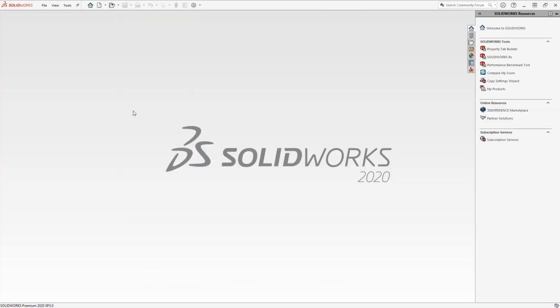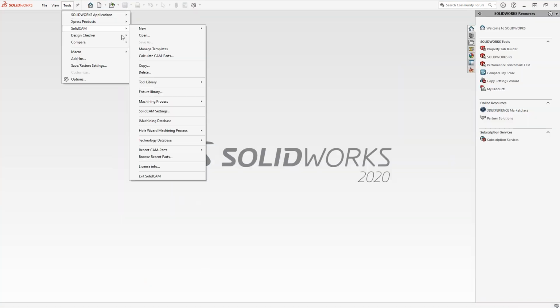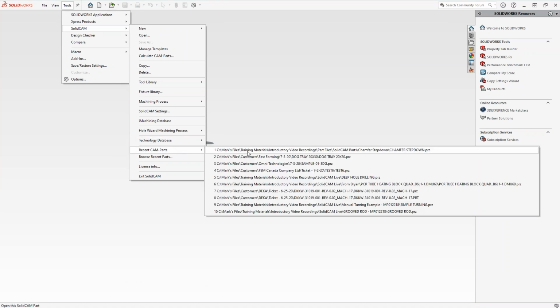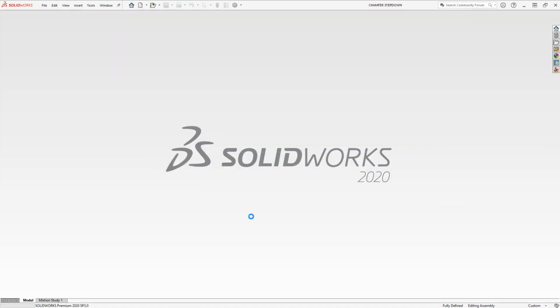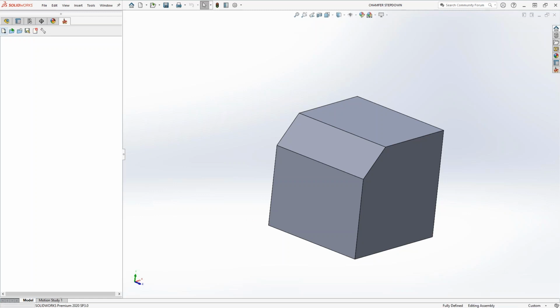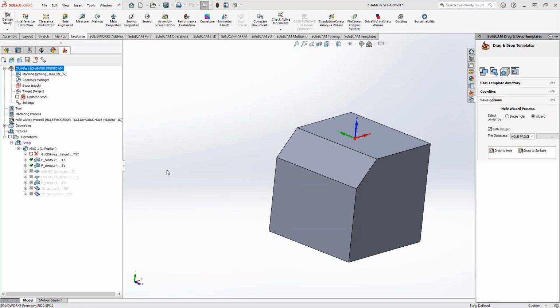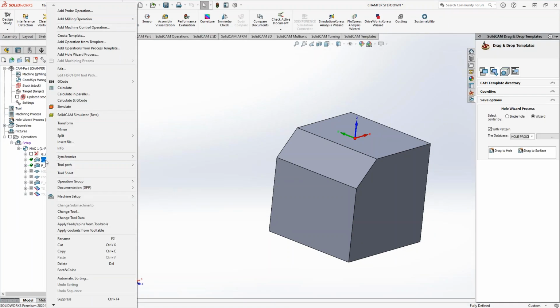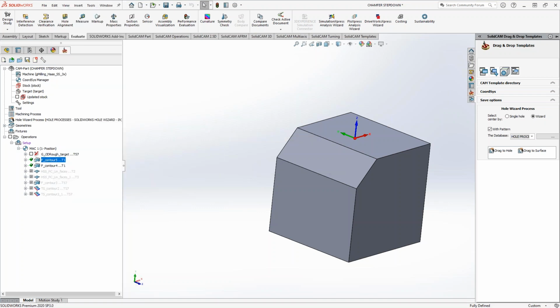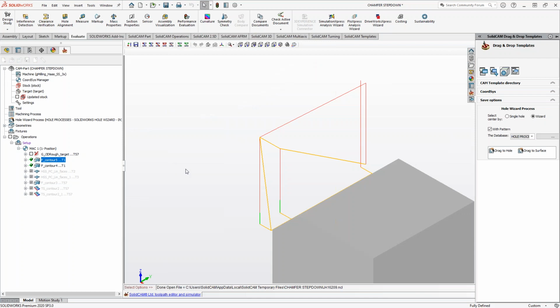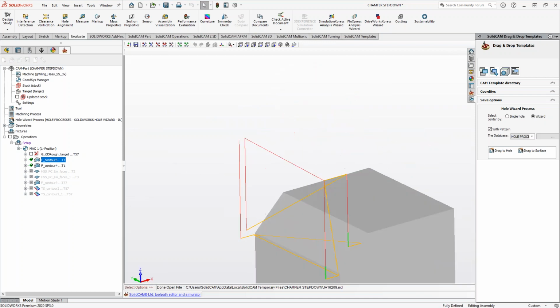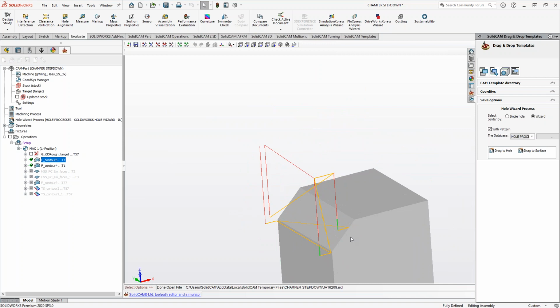Now, with this toolpath editor, like I said, we don't use it very often, but it is very handy. The only ones that you will not be able to edit the toolpath, kind of like what Mark was showing, is 2D machining and 3D machining, and that's just because of the built-in algorithm that we cannot modify that toolpath there, just because it's all about controlling the angle of engagement of the cut and all that there.